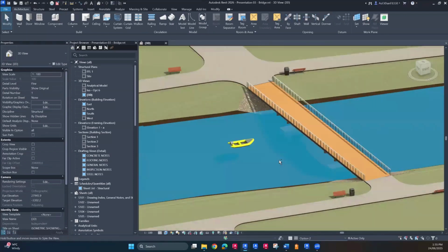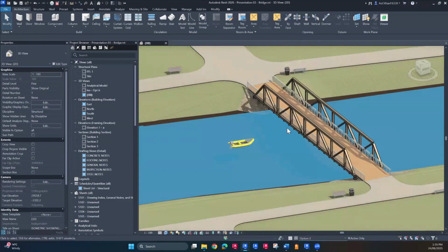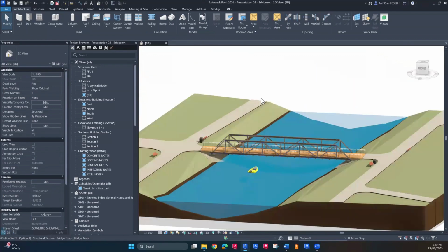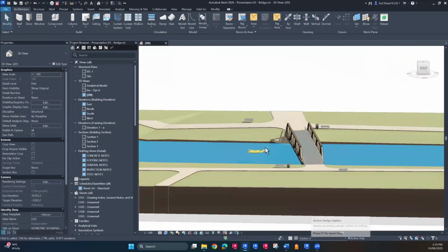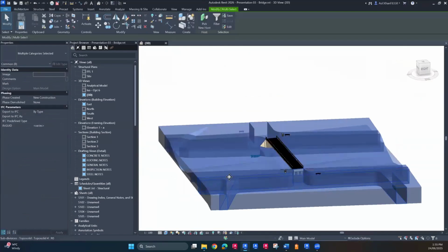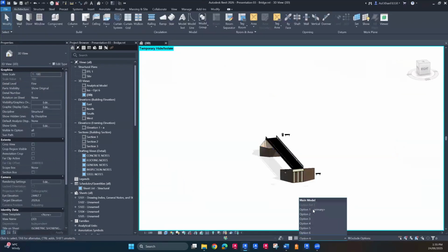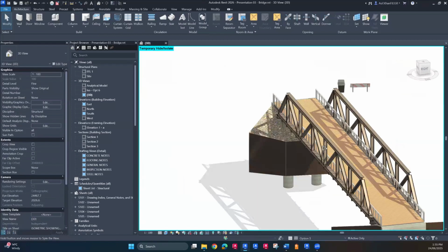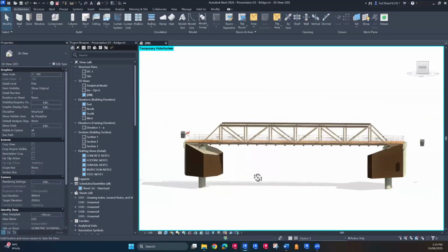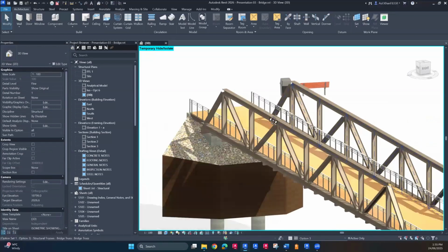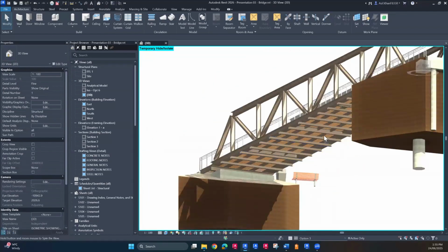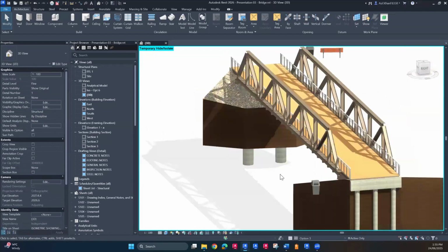Great. So what did we do? We gave them a third option, something like this. In this case, let me show you by hiding it first. We just shifted the piers from the center of the waterway to the side and put in a truss bridge, and that truss bridge has some SHS underneath, which is basically supporting the entire frame. And that was given to the client.